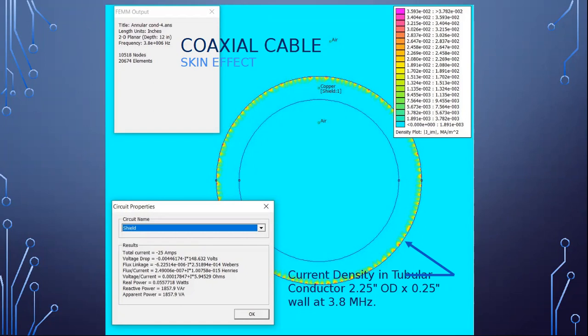We're starting to see discontinuities in the color around there. In real life, that wouldn't happen. The way the model works, you do triangular meshes, and you can't make that infinitesimally small. There's only so small that you could draw the triangles to do the meshing of the model. And so consequently, it sort of falls apart when you get into these crowded areas. But that would be a continuous current around there, and it would still be very high on the outside and less to the inside.